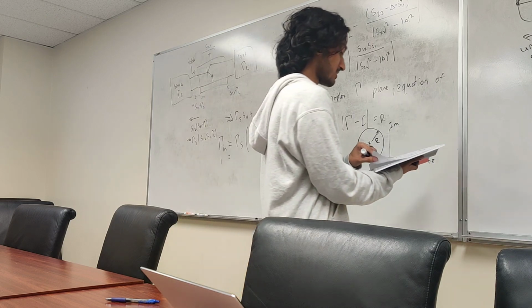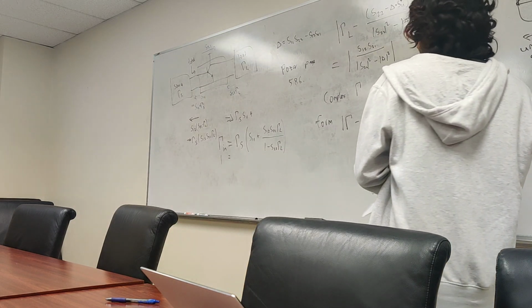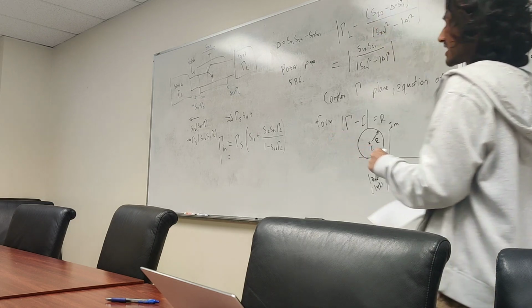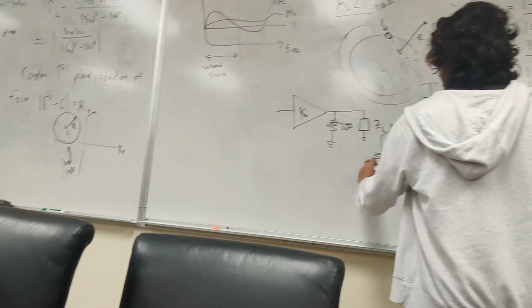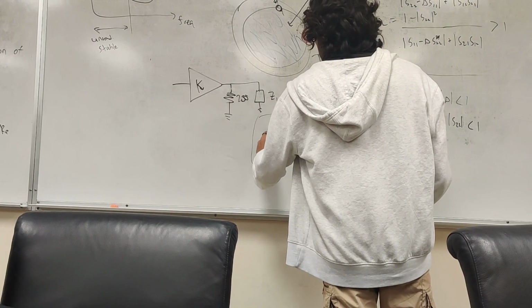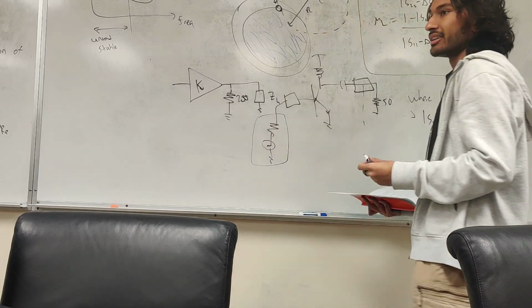So we can't just match things. You have to be careful of how much gain you can squeeze out. And ADS will tell you the maximum gain you have. You make some circuit like this, and it'll tell you the maximum gain. It'll say, hey, first make sure you're stable, then it'll tell you what your maximum gain is. It's going to tell you what source and load networks you need to insert, and you'll insert a load network here. You'll insert the source network here between your 50 ohm source, this is your source here, to make sure a maximum gain is achieved.